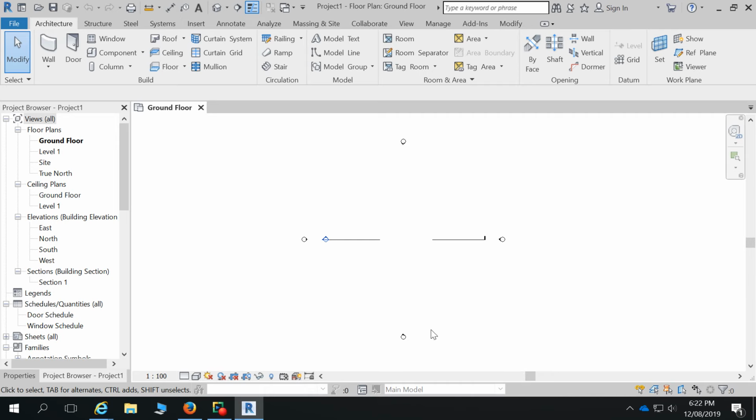The other reason you're given these elevation markers, so one, it's actually putting these views down here in the project browser for us. So when they're placed in there in the template, that's giving us these names or these views down here in the project browser. It also gives us a space to actually know, in all of this model space here, where should I start drawing? Okay, so we're going to try to keep whatever we draw within these markers in here. So if we draw something outside the markers, it'll be behind the camera, so you won't see it in your views.